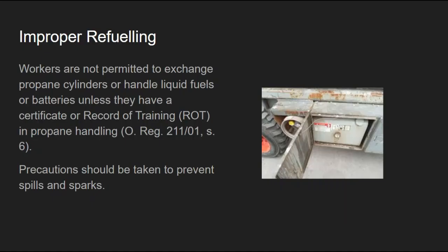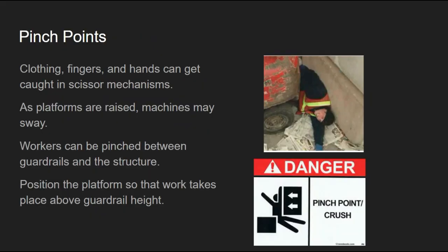Workers are not permitted to exchange propane cylinders or handle liquid fuels or batteries unless they have a certificate or record of training in propane handling. Precautions should be taken to prevent spills and sparks. Pinch points. Clothing, fingers, and hands can get caught in scissor mechanisms. As platforms are raised, machines may sway. Workers can be pinched between guardrails and the structure. Position the platform so the worker takes place above the guardrail height.